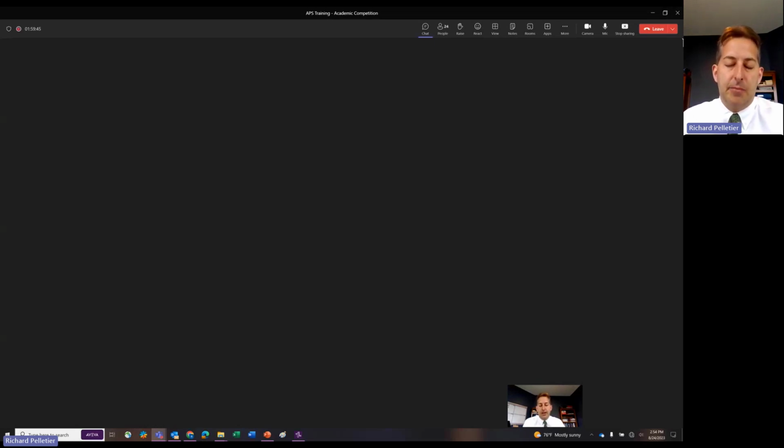Off the top of my head, pump arounds on a column, right? You can do a pump around, but you're going to have to manually simulate that. The column model itself doesn't automatically have a pump around. Same thing with side strippers. You could simulate them with another column model, and it's easy enough to do, but we don't have a side stripper that just automatically attaches to the column model like you would in Pro 2. Right, so those are just a couple examples.